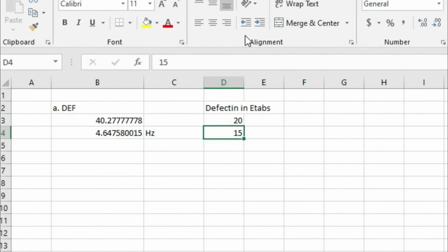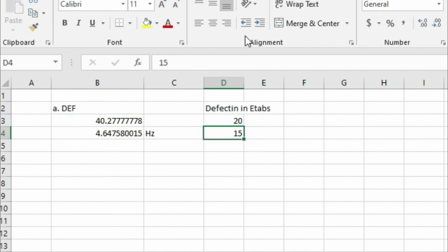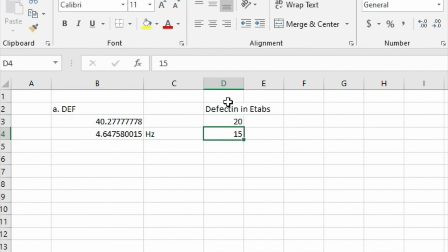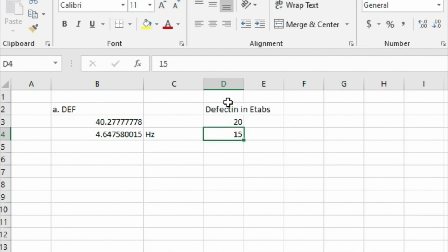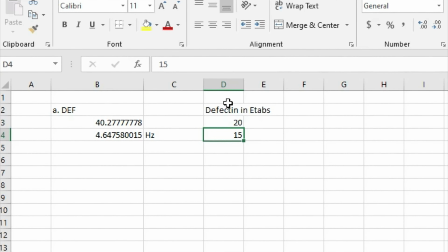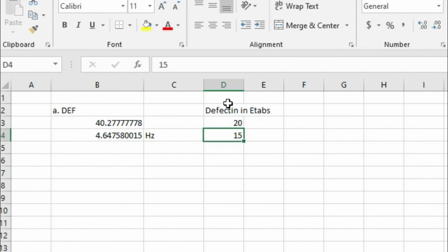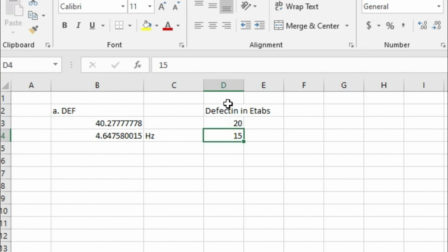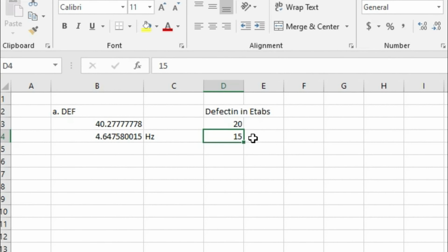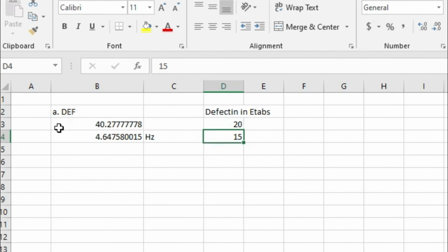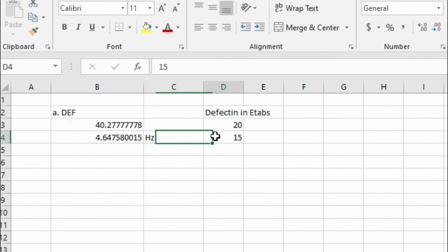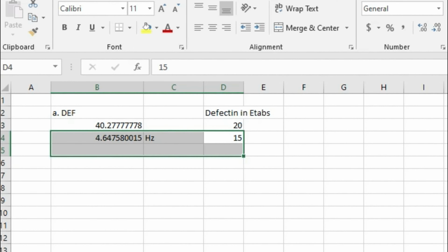For the long span structure, for the long span steel structure or lightweight structure, this is very important to check, not only for local buckling, lateral torsional buckling, flexural buckling, or shear, or other criteria, but don't forget to check floor vibration. I see a new designer or some designers always check only the deflection, not the floor vibration. Is it clear? Yes.